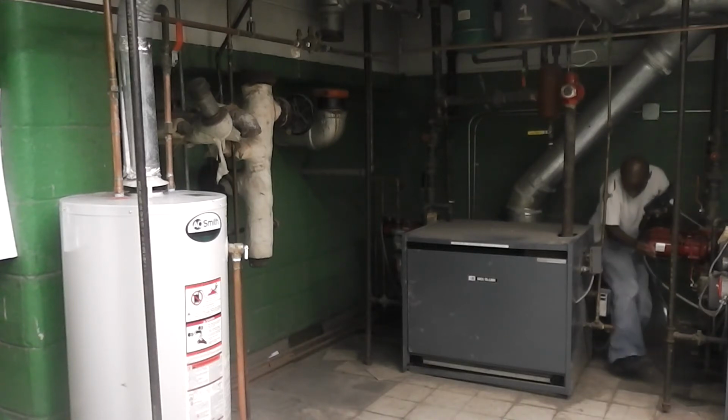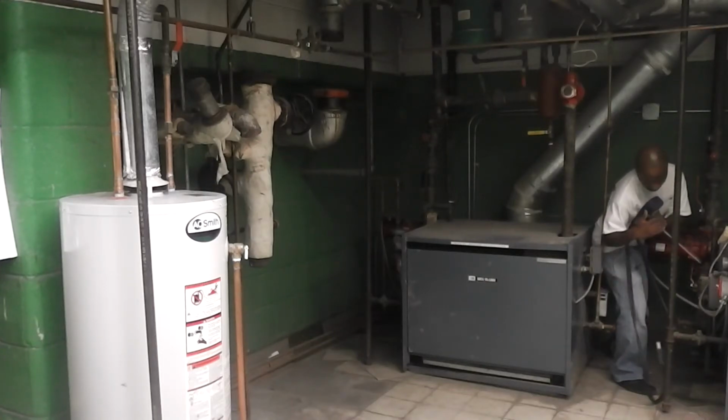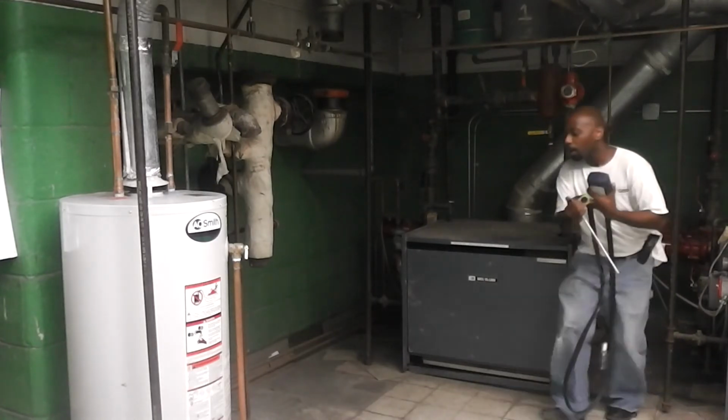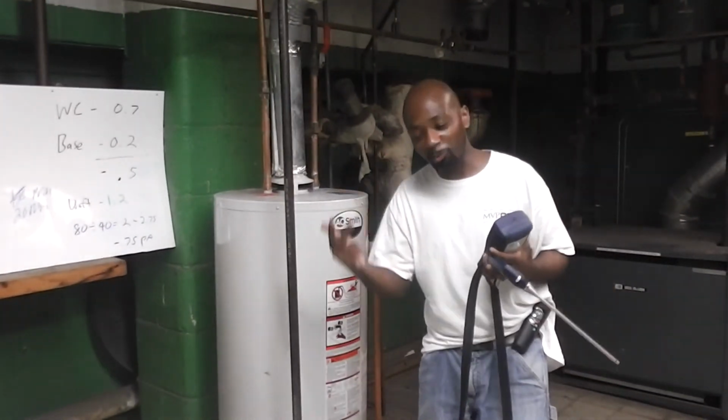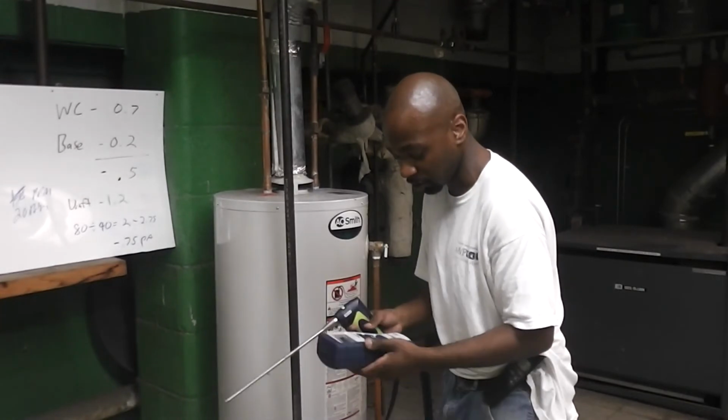Sorry guys. Try not to touch anything. Alright. So we got 22 parts per million. We passed worst case, we passed spillage, we passed draft, we got 22 parts per million for that combustion appliance.